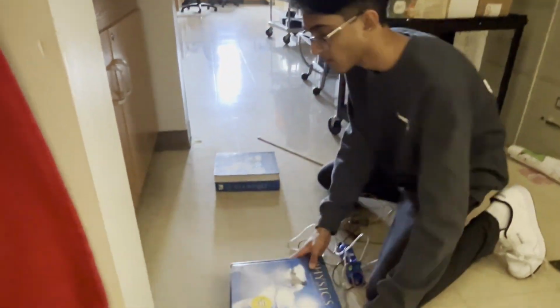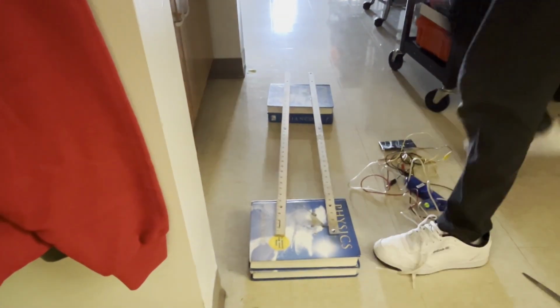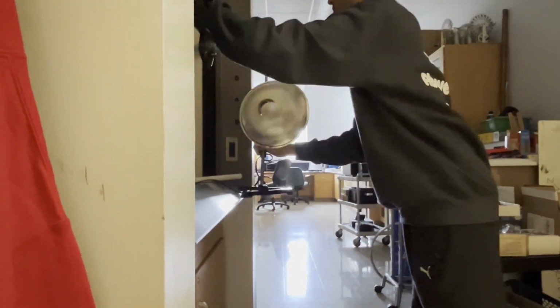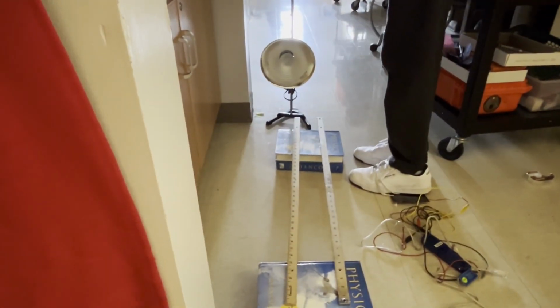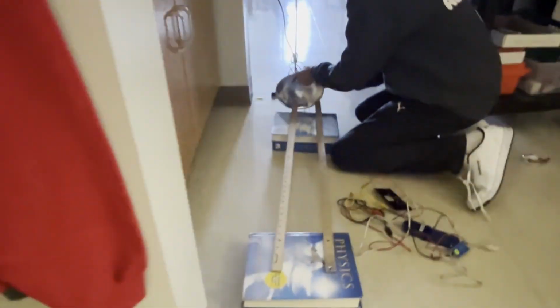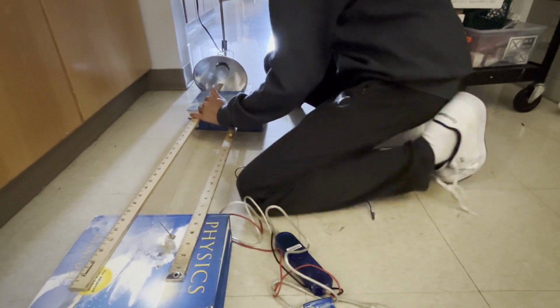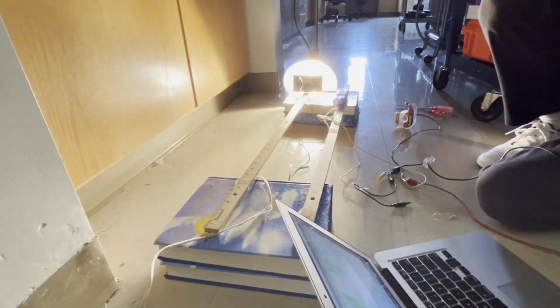The rulers are really important because they maintain a fixed distance of 6 inches, and a second ruler is necessary for the light sensor. At the end, we move the light bulb down to the second ruler and measure the light intensity with a light sensor based on that. Here you can see Arsh lining up the lamp with the ruler, and one major flaw I want to go over is using a 390 ohm resistor because its resistance was way too high, so we couldn't measure any current in our Pasco Capstone data, but once we switched to a 10 ohm resistor, that was fixed.